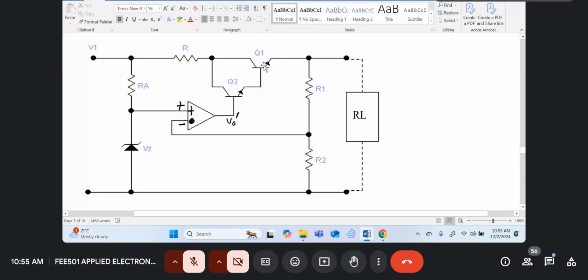If you're using transistors connected this way, it forms a Darlington. And the property of a Darlington is that the current gain of the circuit is approximately HFE of transistor 1 times HFE of transistor 2. It's approximately equal to that. So this is just like one big transistor with an HFE equal to the product of the 2 HFEs.